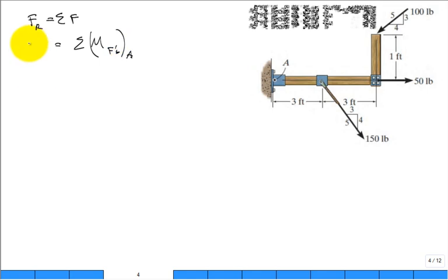Then what we're going to replace is we're going to replace it by the moment that the resultant force, F resultant, generates about point A, plus the couple moment, and the textbook doesn't really put a symbol on that, but I would just put like C comma A, the couple moment. And we know it's a free vector, so we don't even have to put comma A, or the book puts parenthesis A. But I think it may help.